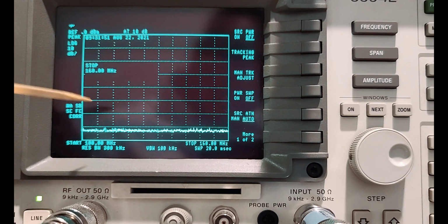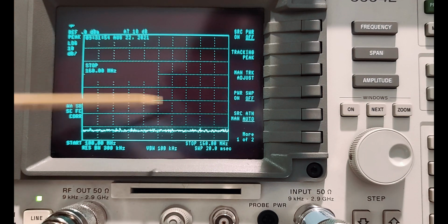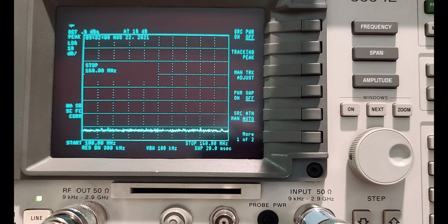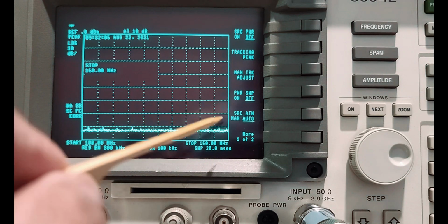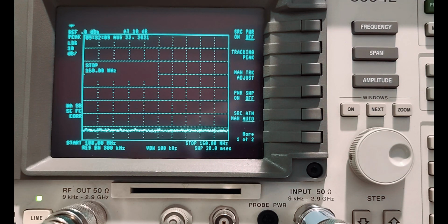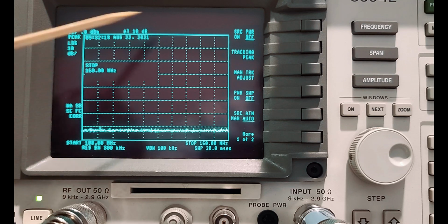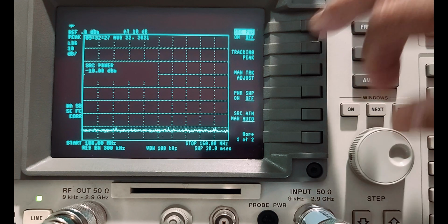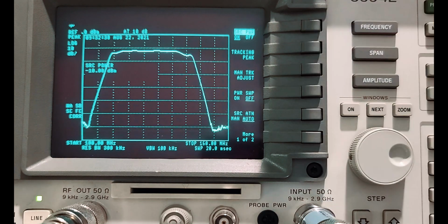And you can then quickly appreciate the amount of time one would save by having this tracking generator do a real-time plot. Because what a tracking generator does is it tunes itself to that same start and stop frequency. So you're not having to reset it up or stage it or any of that stuff. It's fairly real time, it's in lockstep with what you are monitoring from a frequency standpoint, and works in the same clock cycle. Which is great, right? So let me turn this on. That is so fast. And this is real time.